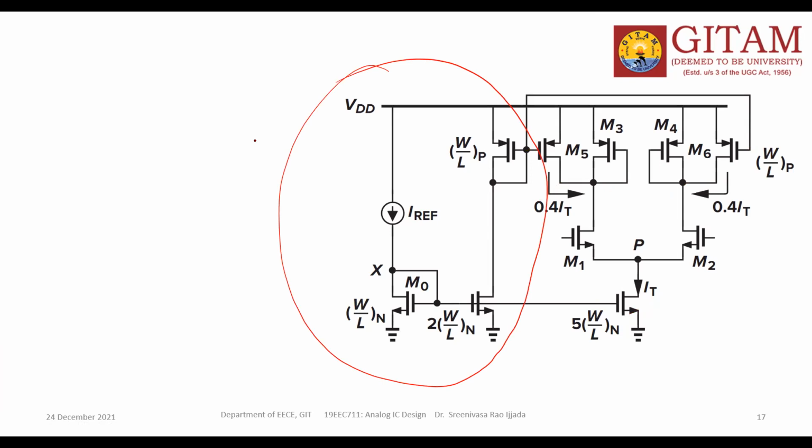So, the current mirror circuit is an application to provide bias voltage to the Gilbert circuit or differential amplifiers. Not only here, wherever, if you take different circuits, you can use this current mirror to bias it. Clear? The difference is, there we already applied VB, but that VB is not independent of the PVT.